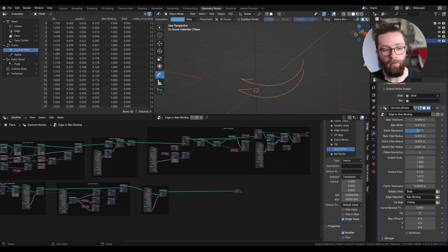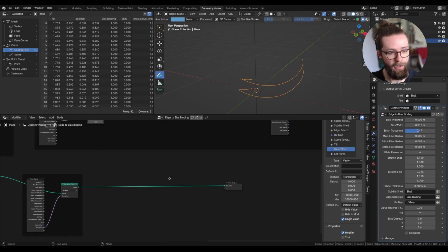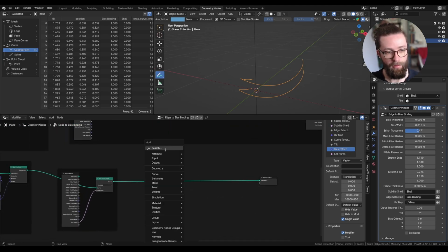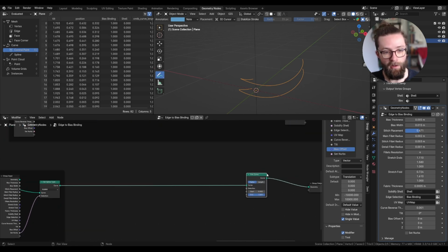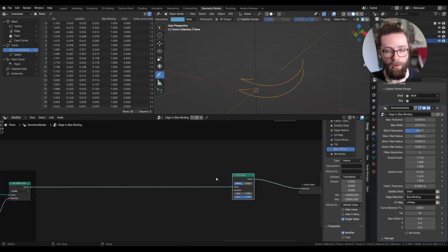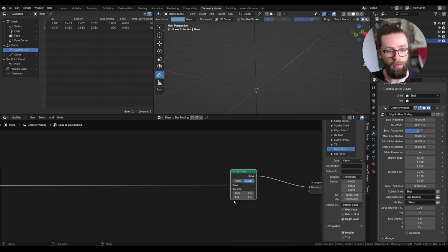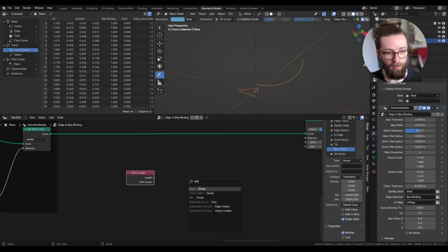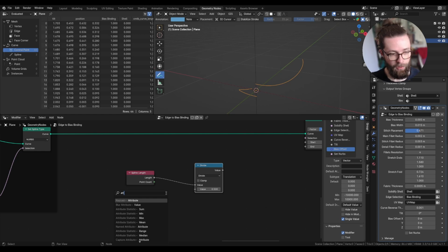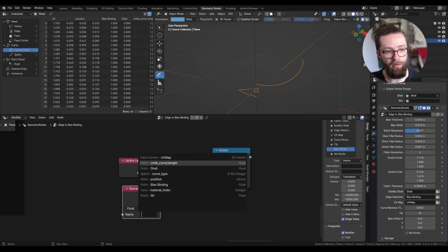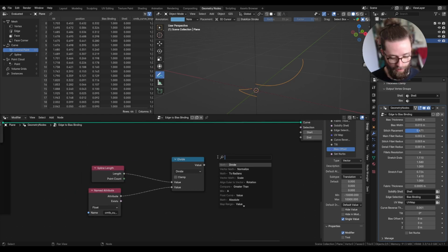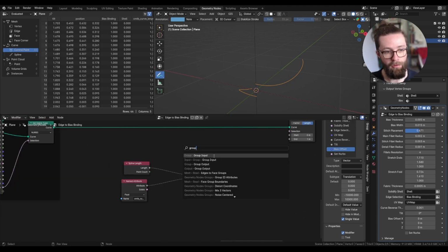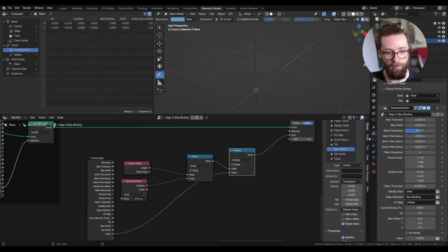So now let's add a step to change the length of the curve with a trim operation. So let's add a trim curve node. And here we could make it consistent with deformation by using the factor, but I want to use the length parameter so that we give a simple input to the user. So for this, we can take the actual spline length, divide this by our attribute for the curve length we created before, cmtb_curve_length, so that we get a kind of factor. And now we can multiply this by a user input, which will be the start value in meters.